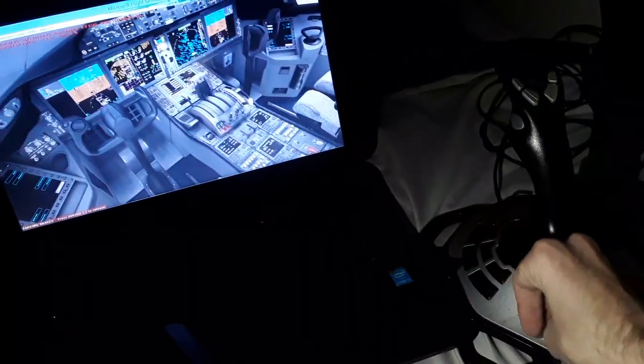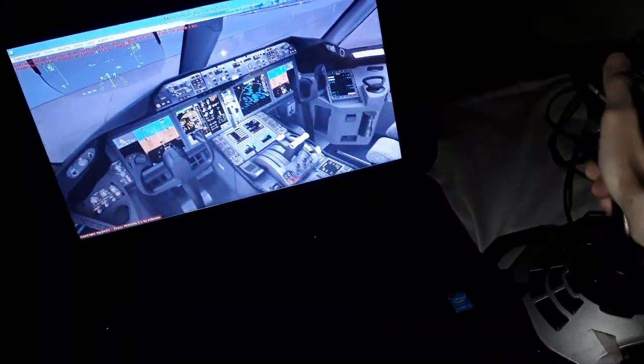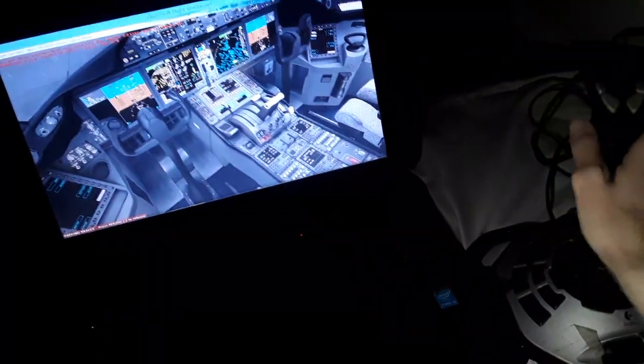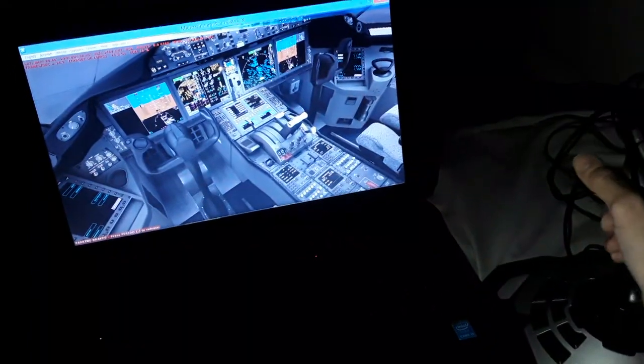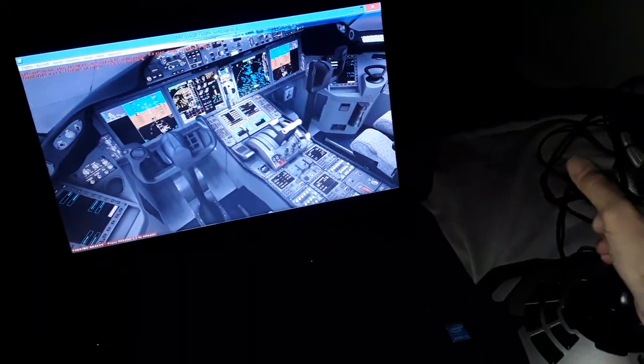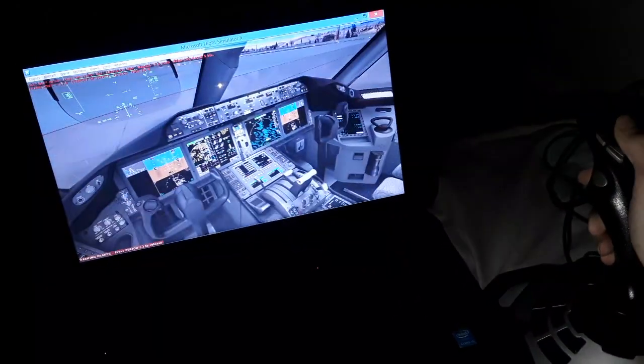Moving up and down. So climb and descent. Rudder pedals left and rudder pedals right. You can see the rudder pedals are used for the vertical tail of the rudder, for nozzle steering and for braking on the ground using the toe brakes.